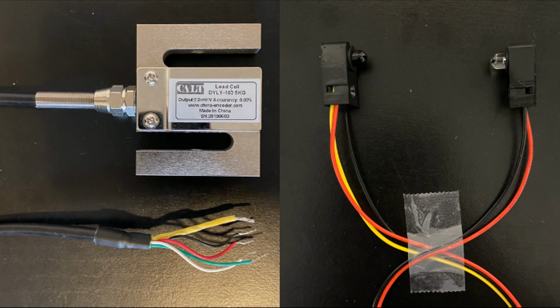This is the load cell and sensor subsystem, and it's made up of two parts, the load cell and the infrared sensors. The load cell is of the hanging S type with an internal Wheatstone bridge and continuously measures the weight of the IV bag. The infrared sensors are used to measure the fluid levels at the alert and change conditions.